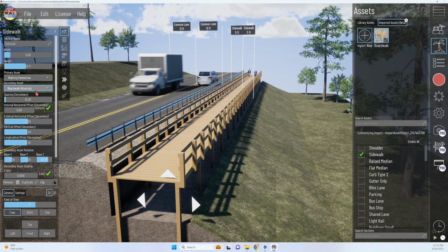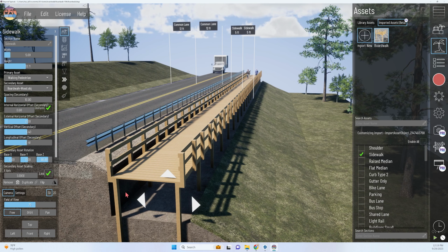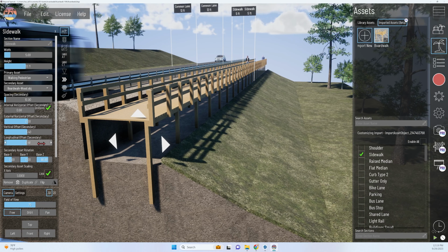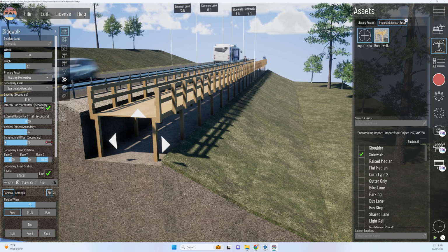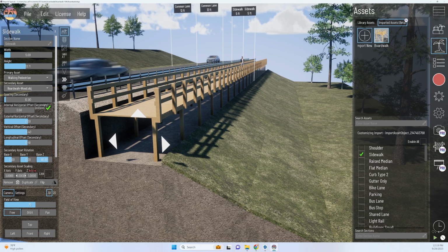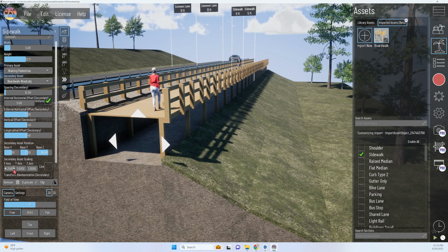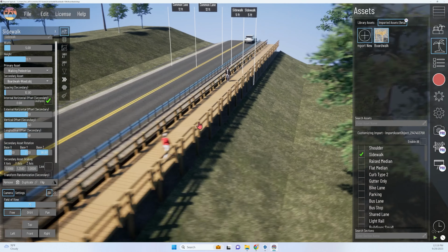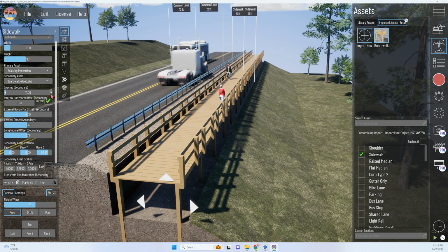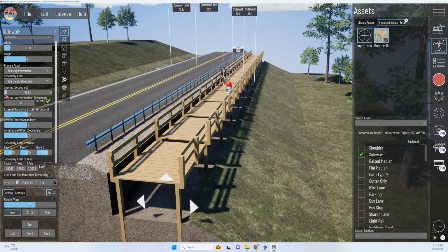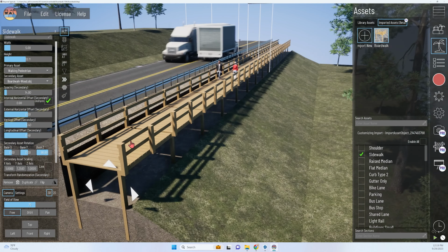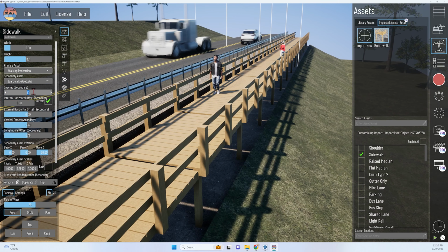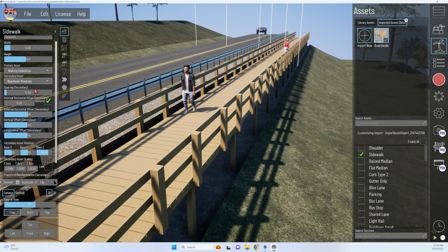We can also play a little bit with spacing and scaling if you do want to see this maybe just at the surface of the front of the section. So what I can do is actually play around with the x-axis scaling, the y-axis scaling, just to make that a little bit longer. And in that case, we might want to adjust our spacing accordingly as well. So what I've done is just basically made that 10-foot section a little bit longer, 12.5 feet or so. So let's type in 12.5.